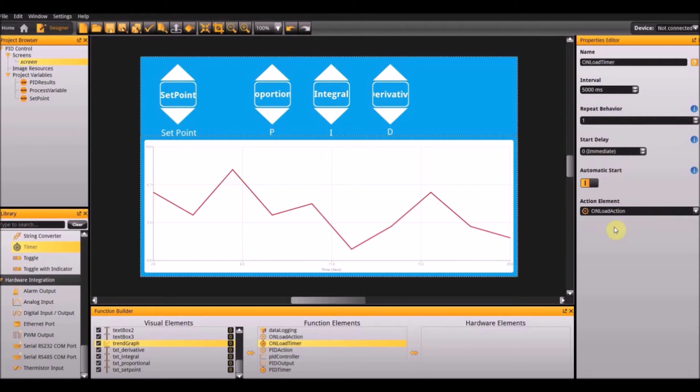The next function element we are going to create will tie the up and down arrows with the numbers and the rectangles in between them, and that will be tied to the PID controller. The first group of elements will be for the setpoint up arrow. We will first need to create a math builder, which will allow how high we can select the number and the rectangle to be, and by how many digits it will change by. So add a math builder to the project.